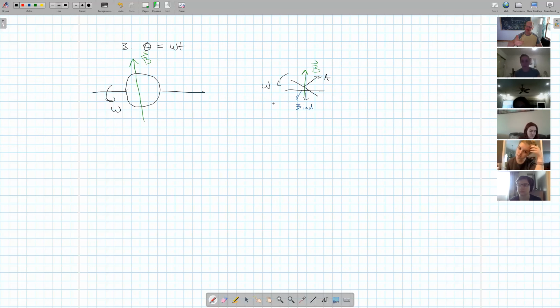So as this thing is rotating, what's happening then is the current is naturally switching back and forth due to the fact that at one moment, let's say the magnetic field is this way, the coil is like this, there is zero. It's then going to start to rotate. So as it starts to rotate, the area is getting bigger, the current goes in one direction, reaches maximum, now reaches here, area is now getting smaller, the external magnetic field points in the opposite direction then, the induced magnetic field points in the opposite direction, current switches in the opposite direction, so this is actually what's creating AC.